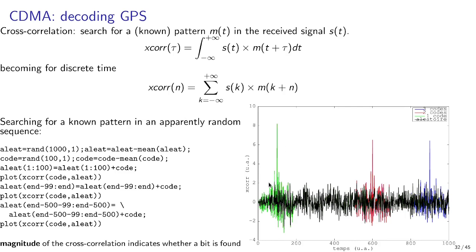Furthermore, let us mention that thanks to the linearity of the cross-correlation, even though we are modulating on the phase, because the cross-correlation is a linear operation, calculating the magnitude of a correlation allows for detecting which satellite is broadcasting with which time delay, as demonstrated in the simulation.